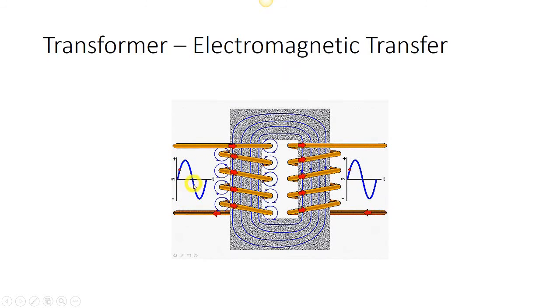But here we have this sine wave, which is causing current to flow in the wire. When the current flows, we're causing this electromagnetic induction to rotate around that wire. And we learned from the electromagnet that we studied that those magnetic lines penetrate this permeable soft iron core, and soft iron can manipulate those magnetic field lines and get them to go in the direction that we want.